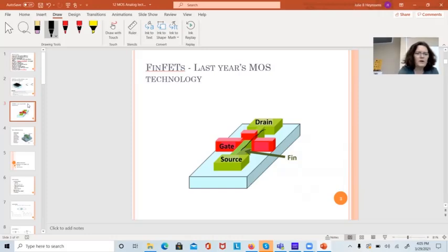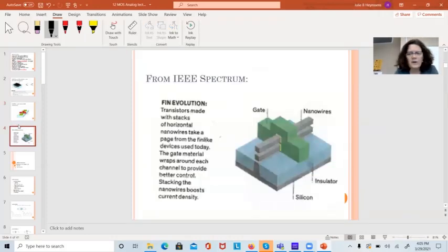To get that worked from about 10 nanometers down to about 5 nanometers, now Samsung's in early production on 3 nanometer devices, which look kind of like this, except the gate is wider because the wires didn't work. They needed what they call sheets, which is just a little bit wider area. They had to make this dimension bigger.